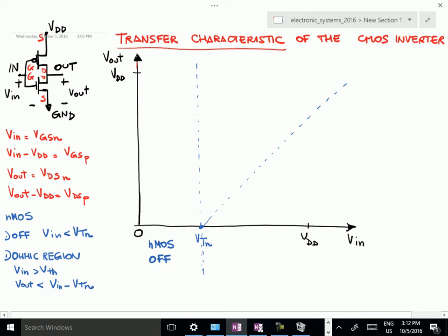Okay, so below, because we are taking the smaller side, below this line, the NMOS is in the ohmic region, and above this line there's no reason to do the rest of the calculation. Of course, the conditions completely divide the space in 3 regions.